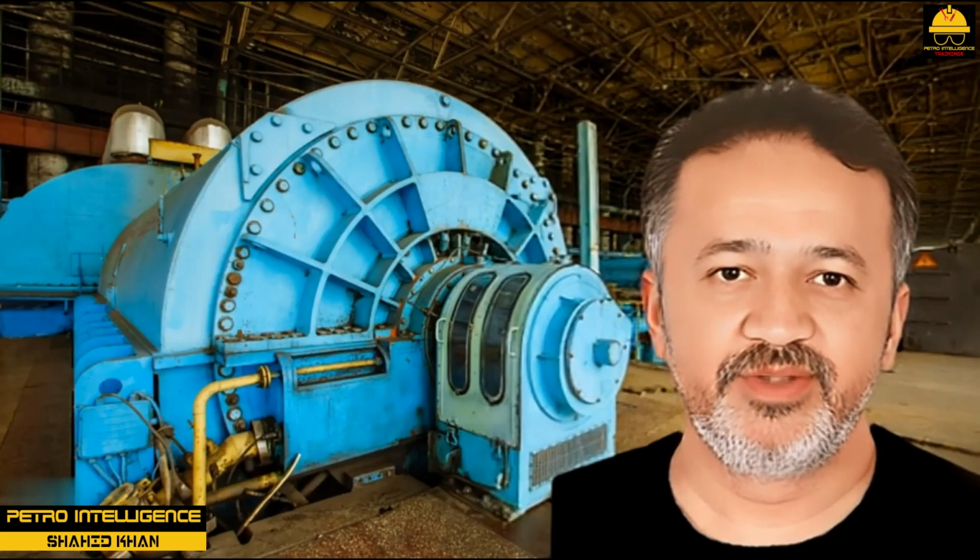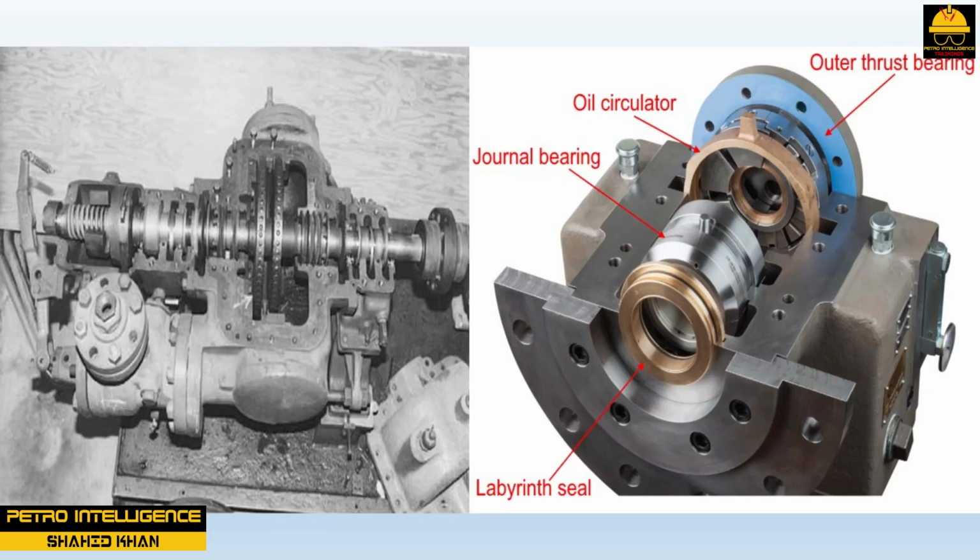Seals. Carbon ring and labyrinth shaft seals are located at the end of each casing along the rotor. These devices are used to minimize the outward leakage of steam under pressure and the inward leakage of air. Carbon rings prevent leakage between the rotor shaft and the casing.